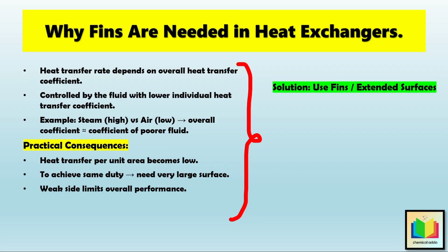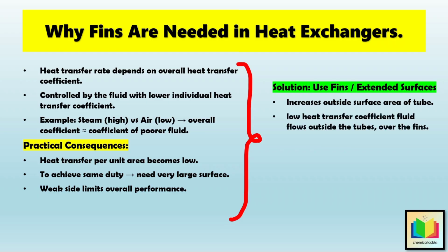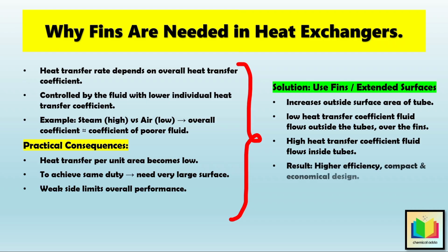Because these fins increase the outside surface area of the tubes, allowing the poor heat transfer fluid to come in contact with a much larger area. And typically the fluid with the low heat transfer coefficient flows outside the tubes, over the fins, and the fluid with the high heat transfer coefficient flows inside the tubes. So by doing this, the overall exchanger efficiency improves significantly while keeping the design compact and economical.